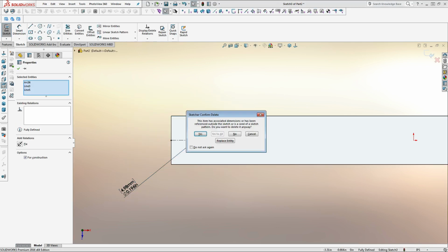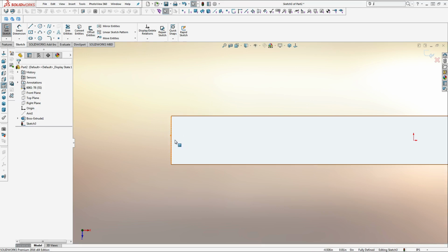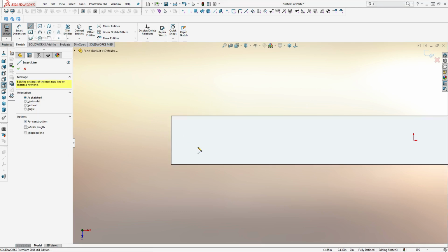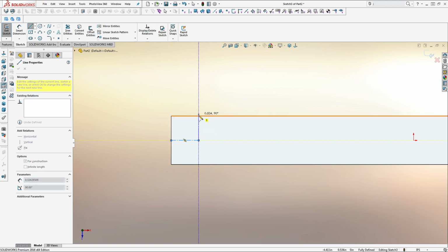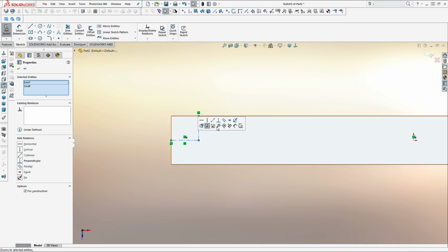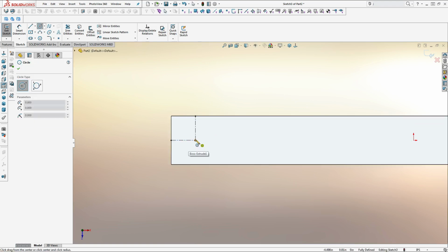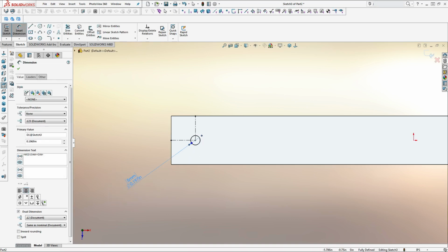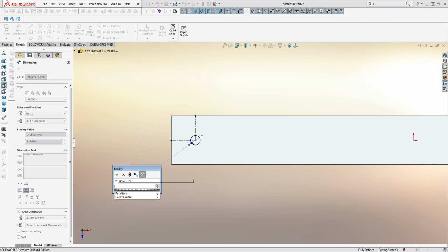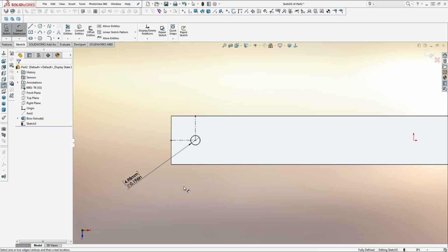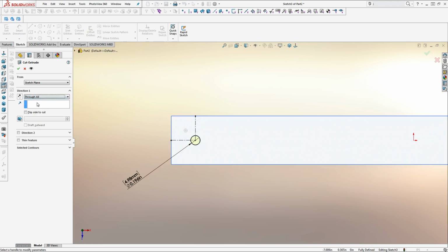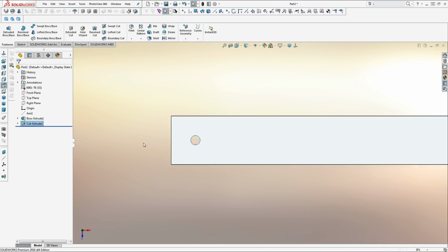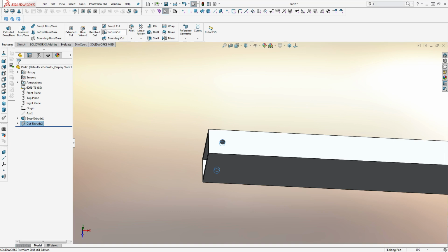And if I were to do it quickly, it saves a lot of time. See, that's a lot faster than making 2 dimensions and making sure everything's in the right spot. Oh, oops, 1 second. There you go, 196. And I'll extrude cut that. So I'm only going to make one, and then I'm going to linear pattern it. So I'm going to go over to my features and go to, where is it, linear pattern.